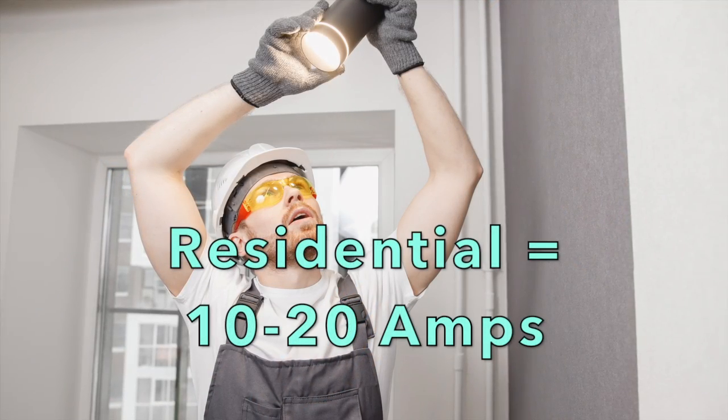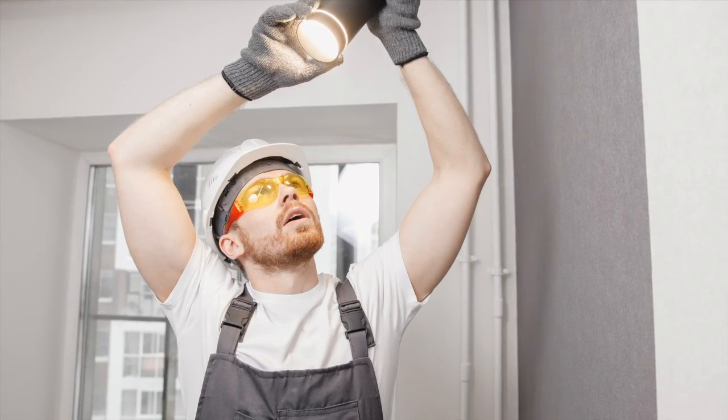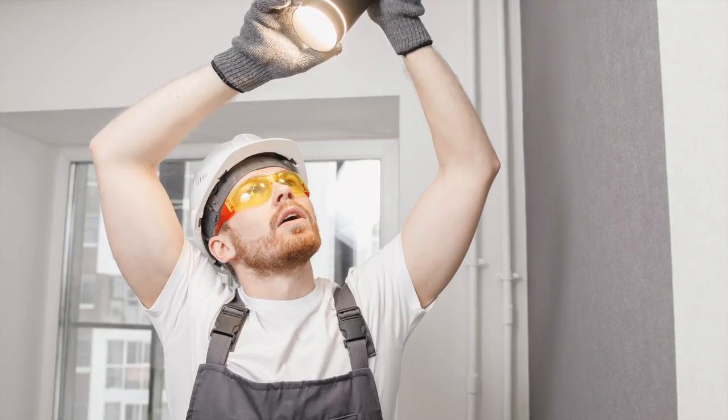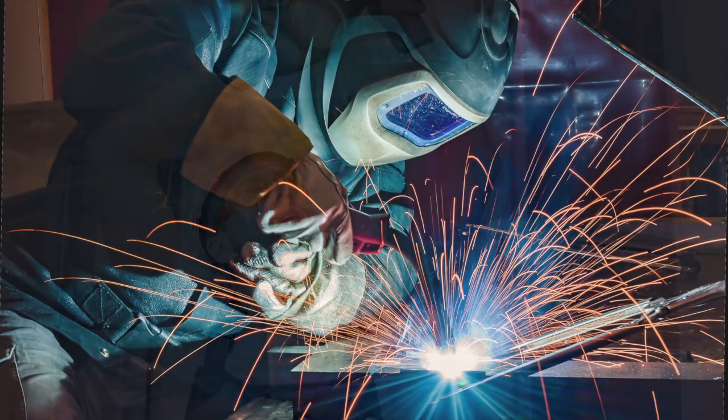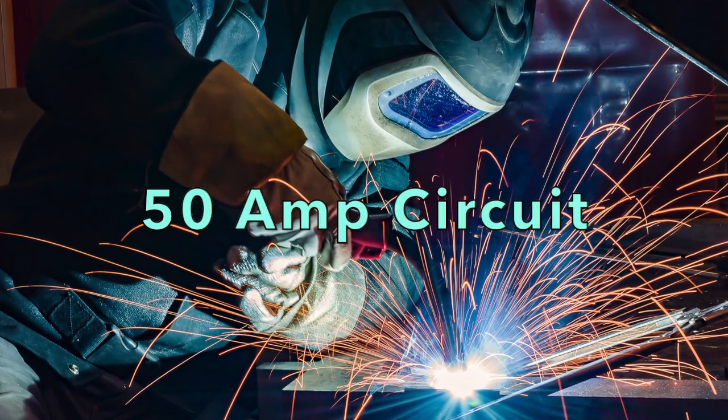Residential circuits typically are designed for 10 to 20 amps. Likewise, many circuits in an agriculture mechanics shop would be 20 amps or smaller for most general purpose applications. Welders and large motors will typically use a 50 amp circuit due to the amount of current that needs to be carried.